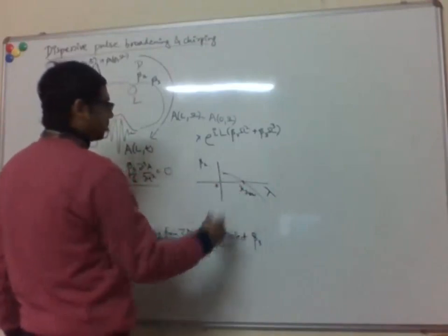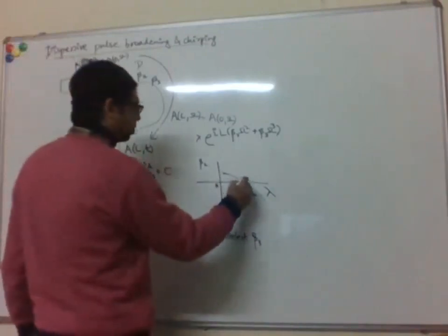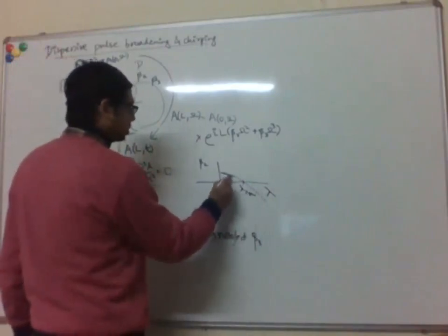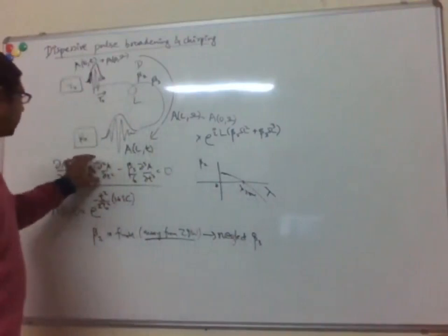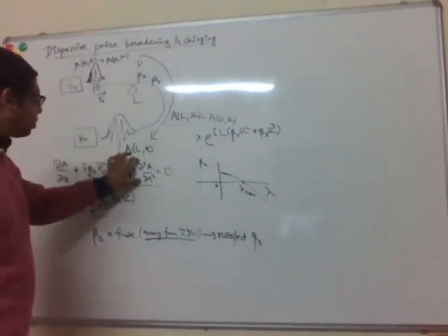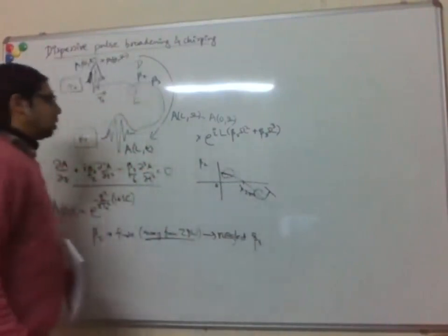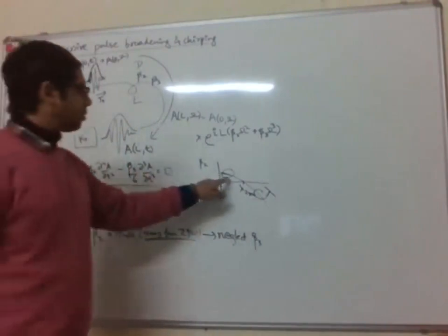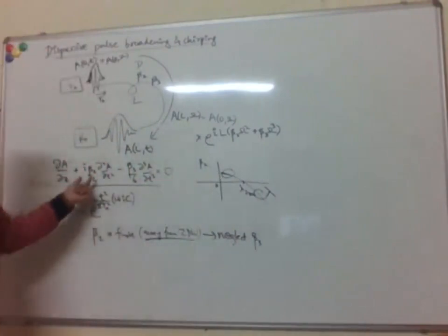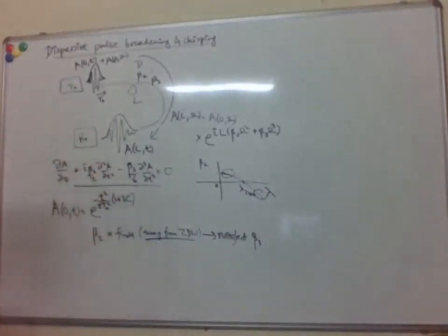So typically we saw that for single mode step index optical fibers, this was around 1.3 micron. So if you operate close to that, then this term will be small, right? Because beta 2 is close to 0. Then you have to include this higher order term. But if you're operating away from that, typically the beta 2 term is dominant over this, right? So I'm saying we are operating here, and we can neglect the beta 3 term in that case.